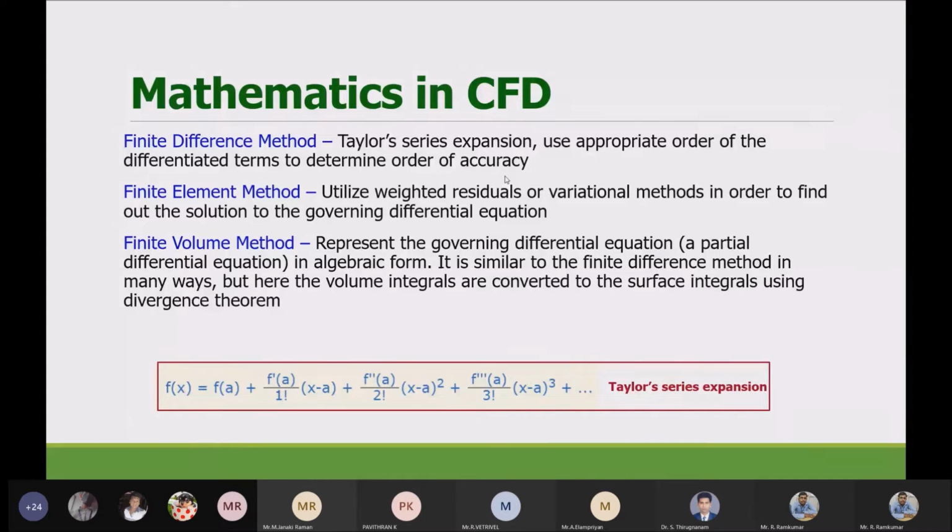And then what you will do is modify the question, that is the differential equation of interest, and add something called a weighted residual and try to solve this problem using various methods. It can be Newton-Raphson, that is an iterative method, or you can form something called a stiffness matrix, whose short form is again force is equal to stiffness into displacement. So you will bring all of these difficult terms that I told you earlier into just these three terms, and then you will try to solve either the force or the displacement, because the stiffness is mostly associated with the material property.